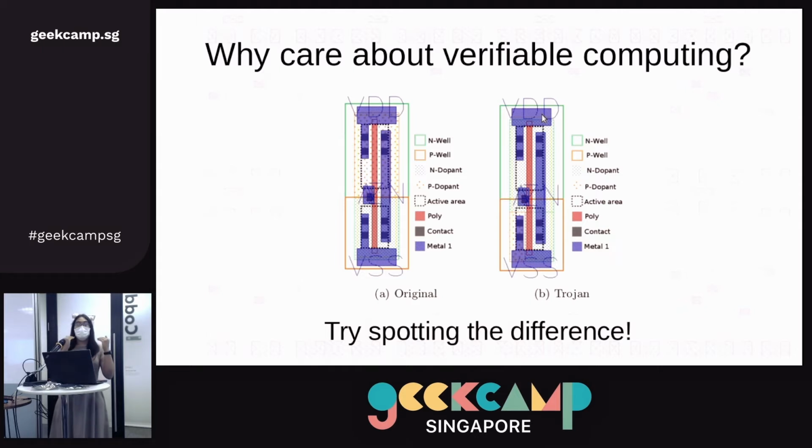But see, ion implantation, doping, is a very precise process. Doping is a process of changing the electrical properties of a semiconductor by introducing dopant atoms like boron or phosphorus. In that manner, you actually change how the base silicon itself conducts. By building and doping various layers of silicon, you can actually build transistors.